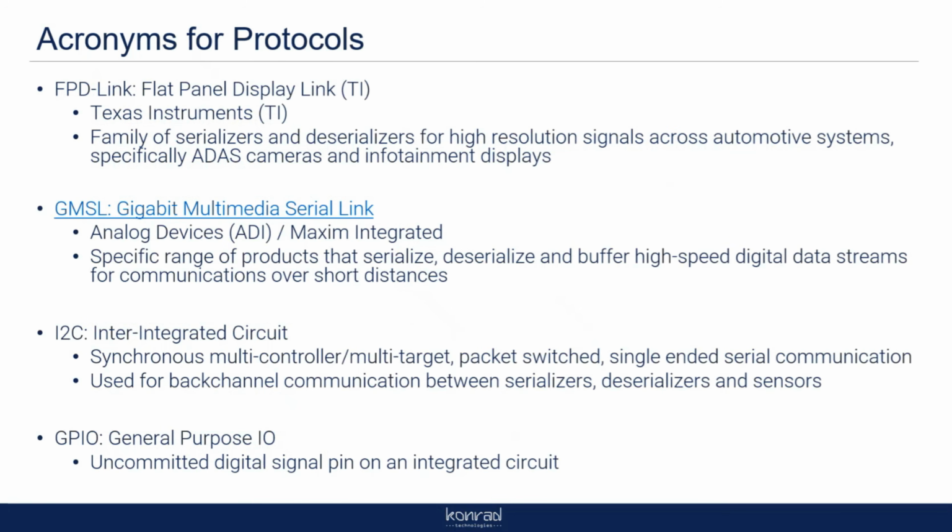So the next thing up is the main protocols and the main SerDes chipsets. And so that's FPD-Link and GMSL. TI, or Texas Instruments, is the one who makes FPD-Link. And just to confuse everyone, FPD-Link started out as only a display thing. So it actually stands for flat panel display link. They kind of got rid of that when they started using it more for cameras too. But this is the one you have to really watch out for chipsets.